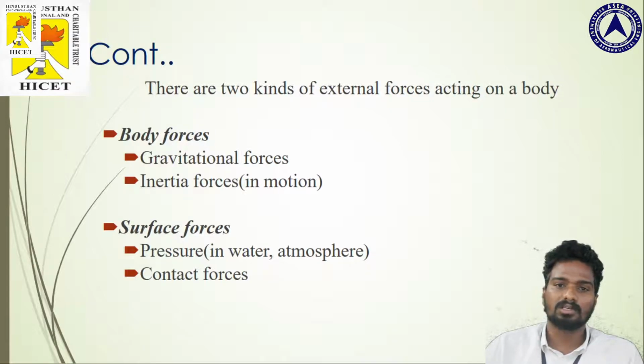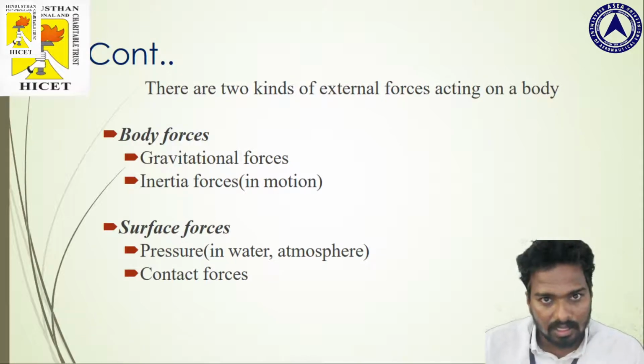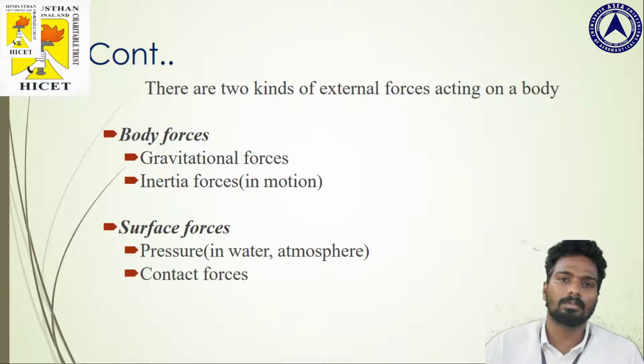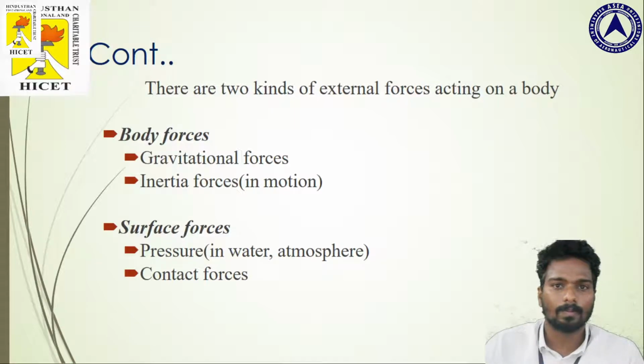The second kind of external forces is surface forces. Surface forces are mainly due to pressure. For example, pressure exerted on any body due to atmospheric pressure in the air, or fluid pressure. When the body is kept underwater, the body may experience the pressure due to the water. And the second one is contact forces, which are mainly the external forces, mechanical loads, or loads due to external objects or external bodies.